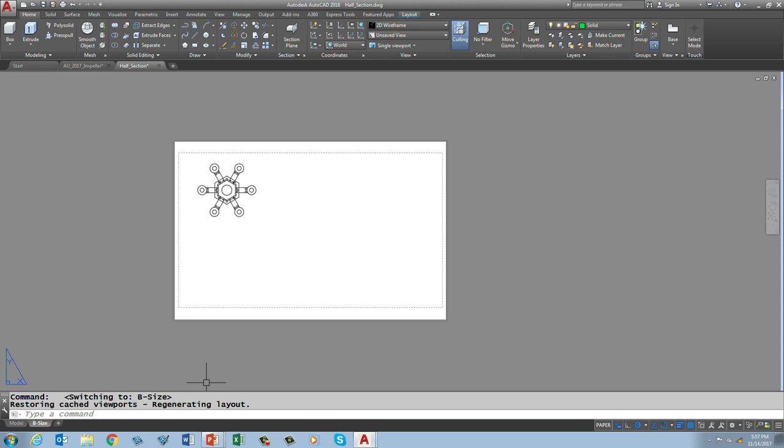Jay, one question. Creating these, if I went back and changed the model, would it update the section? Right, if we have time, we'll edit models. Remember, there is directional associativity. If you change anything in any of these models, this drawing view will update. Okay, that's the power of drawing views. Remember all the other stuff I showed you, sole view, sole draw, flat shot? None of that changes. This all changes when you edit the model.